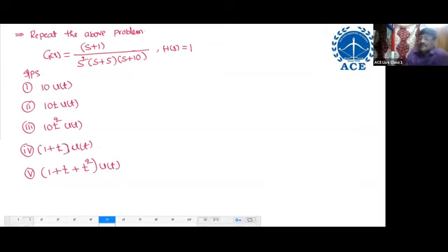Listen, whenever they give a parabolic input, you should be careful. Whether it is in the standard form or not, we should observe very carefully. For example, here, what is the type of the system? S square means type is 2. Now find the steady state errors. Here t power 0, type is 2, type is greater, so 0. Here t power 1, type is greater, 0.